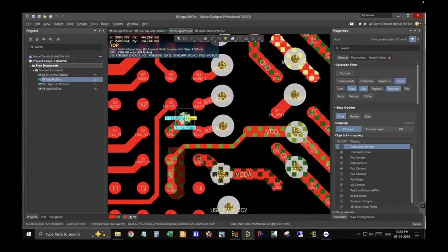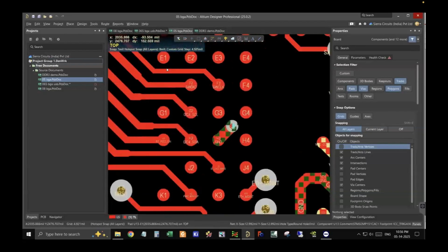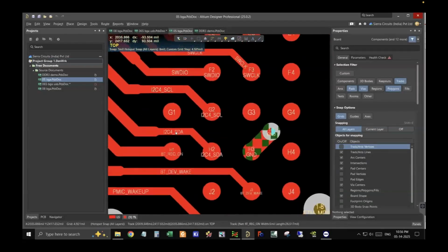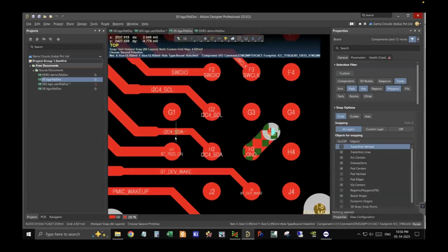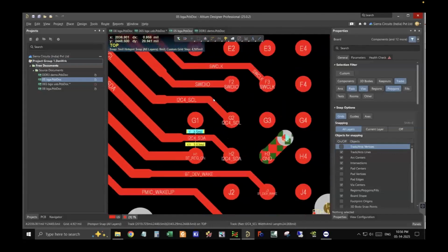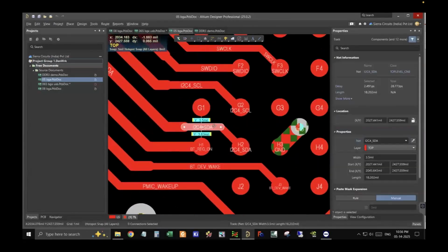And then coming to the line widths. As you can see over here, this is now 3.5 mil with the spacing of 3.5 mils on each side. So that is possible with a quarter ounce foil on the external layers. Another thing you must have noticed over here is the line width is small initially, which is 3.5 mil, and then it increases.